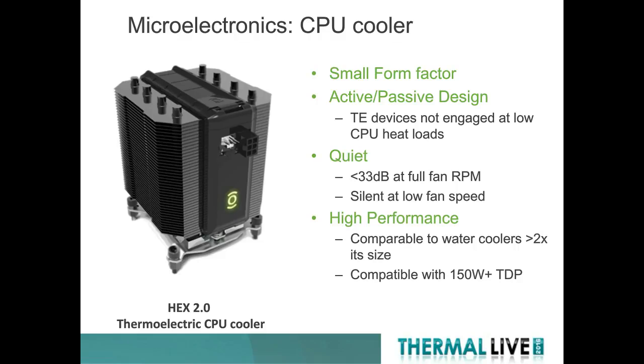So this particular cooler is called the Hex 2.0, and it's thermoelectrically enhanced such that in low power consumption modes, where the CPU is at idle or under very low taxation, this cooler acts just like a normal air cooler. That's enabled by what we call the active-passive design, where the thermoelectric devices are simply not needed.